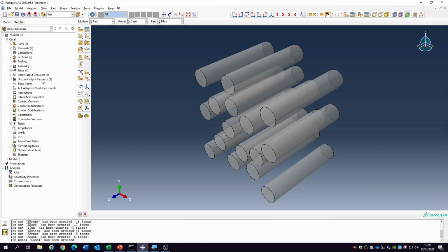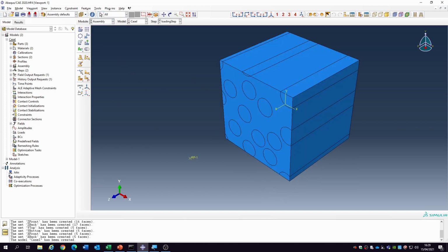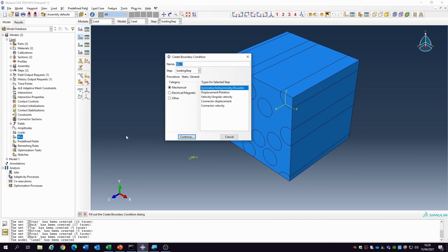So we've got everything. What we're going to do with case 1, again, the assembly module is fine, so I'm going to constrain the back and fix the front. And so I'm going to apply the boundary condition. We're pulling it in the X direction, so double click here. So this will be fixed back, okay, fixed Z back. It will be an initial boundary condition.